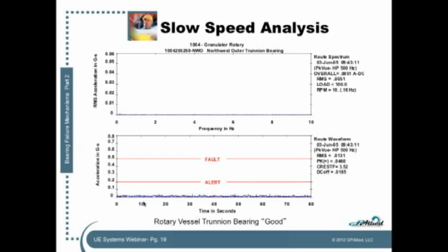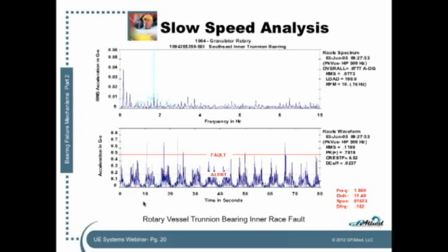However, we move to one of the other bearings on this same machine and we find that there are lots of things going on. The spectrum is full of activity. We'll talk about the activity in a moment. And the waveform is full of activity. And you can see in the spectrum we have all these little blue spikes. And for those of you who are not familiar with vibration data, these are called peaks. So we have all these little blue peaks.